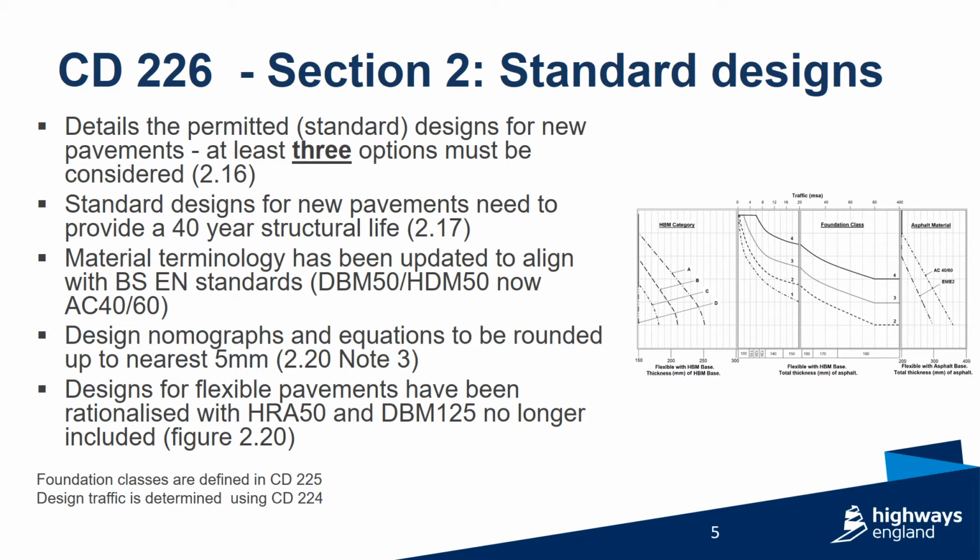Flexible pavements with a lower base layer containing a hydraulically bound mixture. These are designated as flexible with a HBM base. Rigid pavements can be continuously reinforced or roller compacted concrete pavements. Clause 2.17 requires standard designs for new pavements to provide a 40-year structural life.